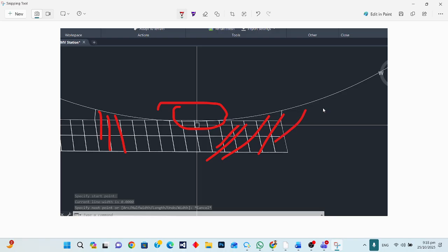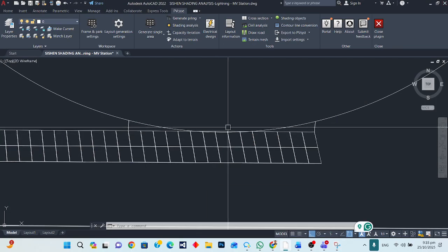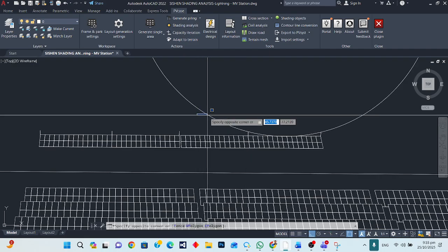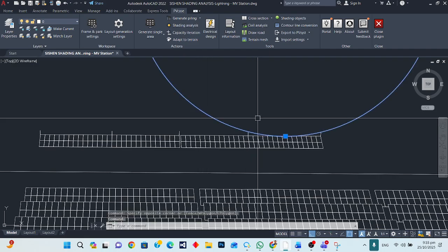Basically, under the rolling sphere, the area is called the protected area. But over the rolling sphere, the area is not protected, and strikes are possible in that area. So now the other option is that we have to reduce the distance.